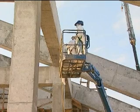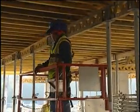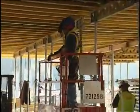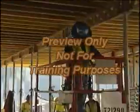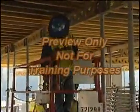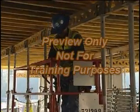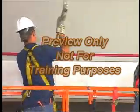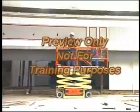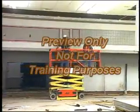Fall protection is required for all personnel that perform work on a lift. If the lift is used according to manufacturer's guidelines and all safety precautions are followed, the chance of a fall is minimized. All scissor lifts require fall protection. Guardrails that are properly designed, maintained, and meet OSHA guardrail requirements are sufficient fall protection. If the guardrail does not meet OSHA standards, or if an employee leaves the safety of the work platform, then a personal fall arrest system utilizing a full body harness is required.